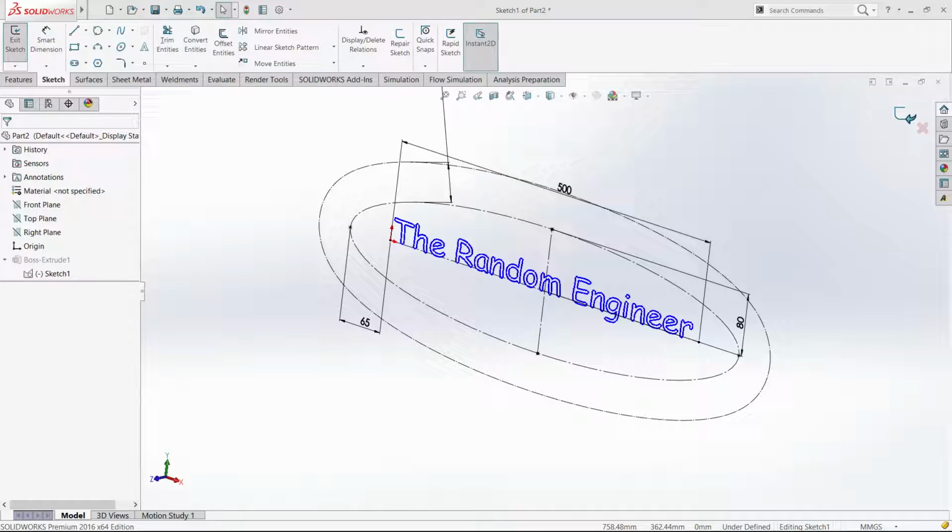with the words. But right now it's telling me there's a warning because, as you saw before, I selected these two lines, these two contours for the feature, and since I made it for construction, it's like they are not there at all for the feature.